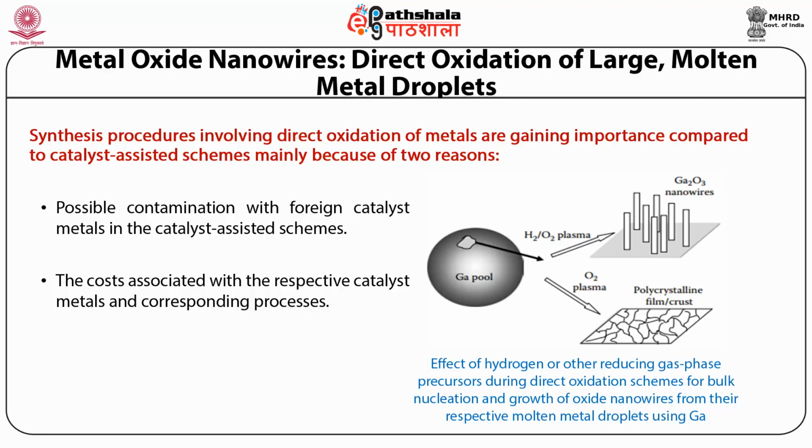Further, growth of metal oxide nuclei via vapor-solid attachment leads them to a one-dimensional structure. High density of nucleation followed by growth from large molten metal clusters results in a flowery morphology in which a high density of nanowires emanates from one point.